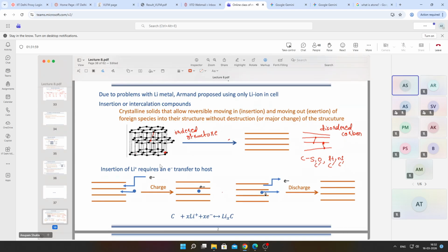During discharge, lithium ion will come out, so it will de-intercalate or exit out of the graphite particle. When it goes out, a positive charge goes out from the structure, so an electron will leave, and that will lead to the discharge of the negative. So this is usually the negative electrode in a lithium ion cell. Okay. Where is this charge stored? So this charge is spread over these carbon atoms. One electron is spread over about 6 carbon atoms.